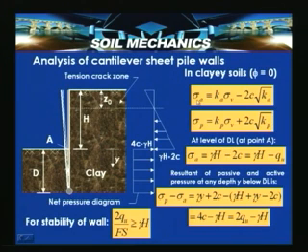So, in clay soils sigma A is equal to Ka sigma V minus 2C root Ka, and sigma P is equal to Kp sigma V plus 2C root Kp. At the level of the dredge line, that is at point A, sigma A is equal to gamma H minus 2C, that is this pressure ordinate is gamma H minus 2C. And then the resultant of the passive and active pressure at any depth y below the dredge line, that is we are now trying to come here.